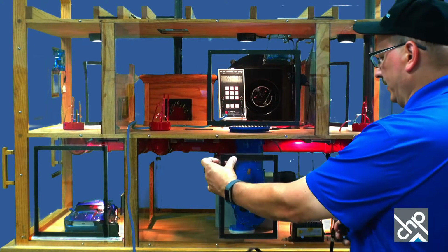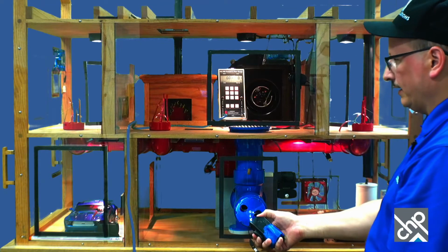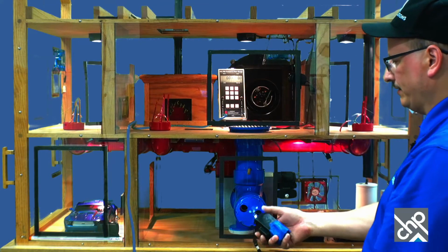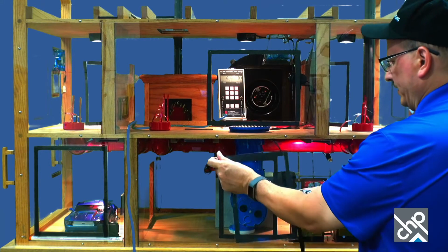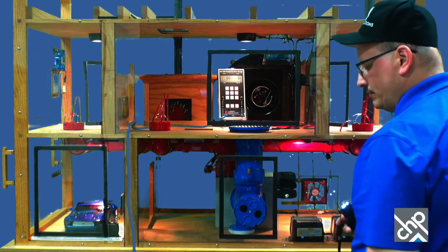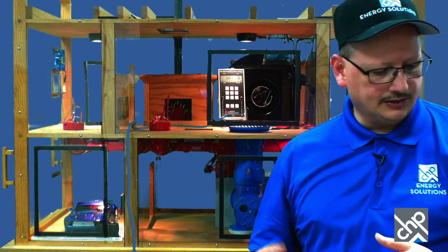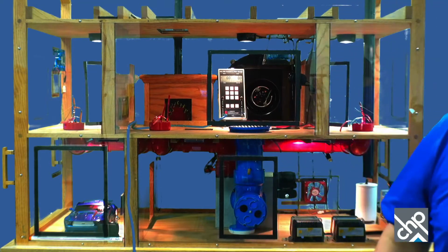You can make leaks in the duct here. So if I go down here, it'll actually pull the smoke in the return leaks, those kinds of things. And we have dampers. We can control how much air goes to each room. But with the forced air duct, you can see how it affects things when we talk about duct leakage and door closure, those things.